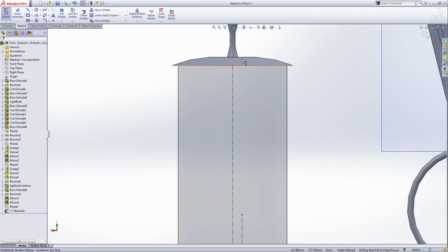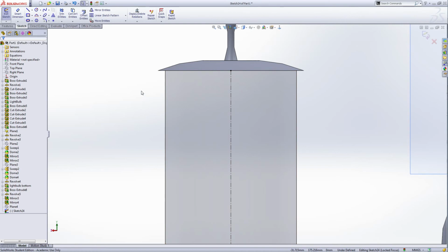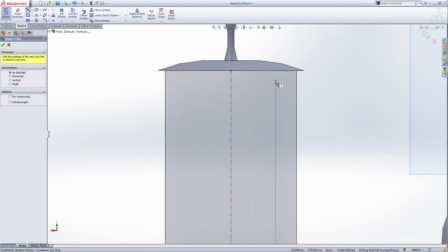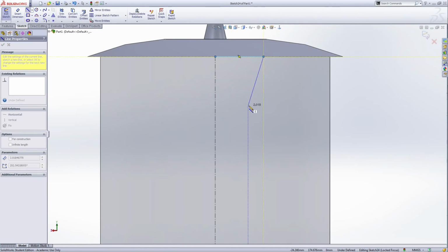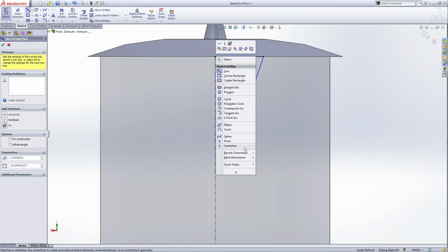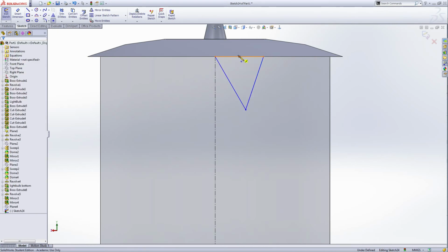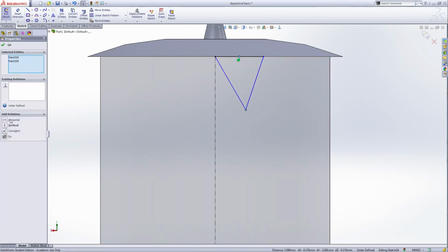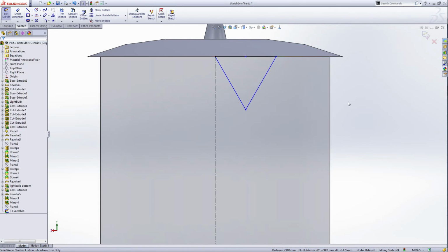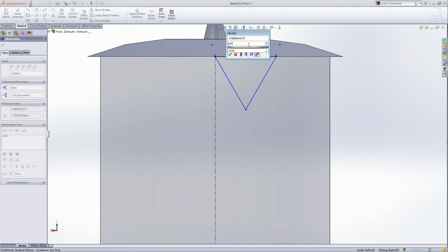So we're gonna make another one on the top of this. So also we use the line, draw a triangle from this point. Try not to give them dimensions. Only draw a triangle like this. And click the middle point here. Okay, select, and at this point hold Control and select this one and make them vertical. Okay, now I want to fix the distance of this. So the distance of this edge is also pi divided by 2.